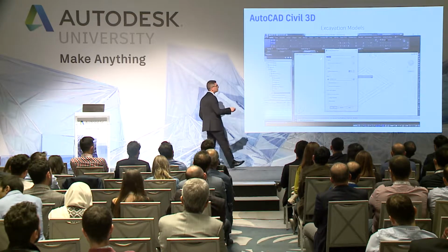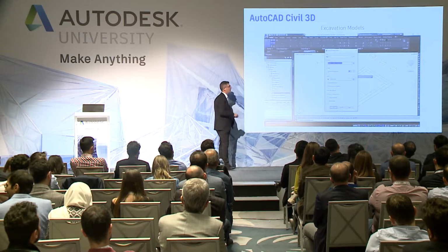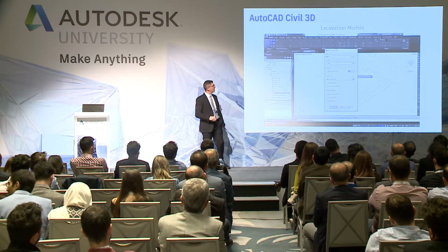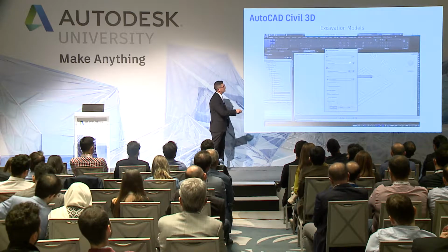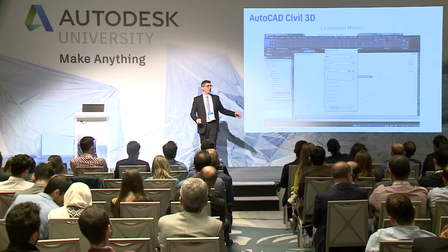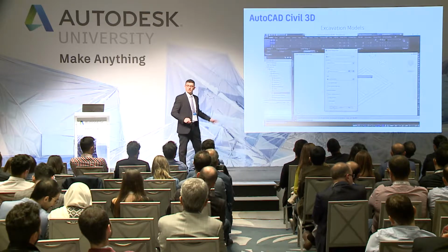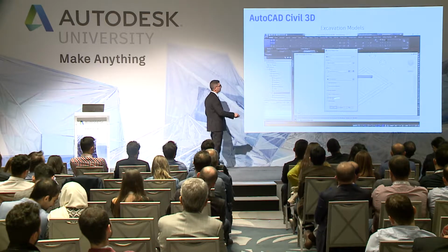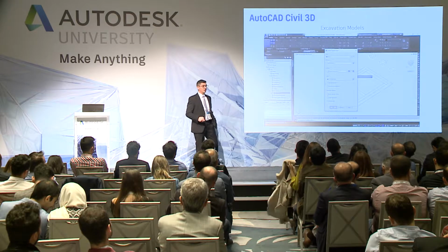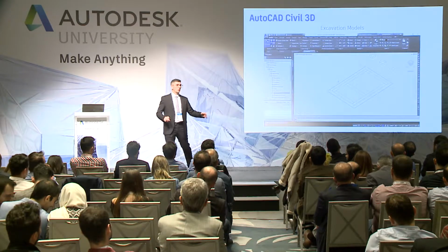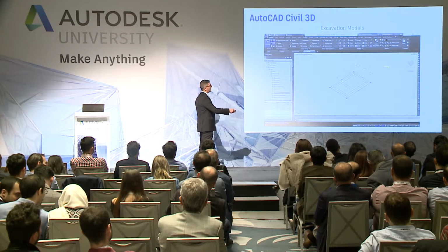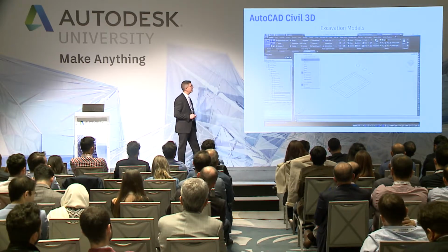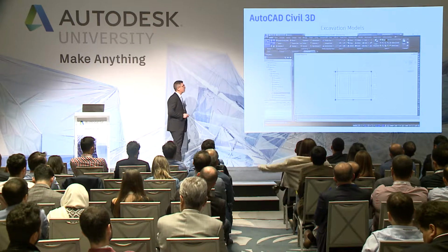This is a site. It's a special part of the Civil 3D tool space. But the basic is the name, and again, the style. The style is the color that I want to see inside this building. And again, the elevation. I can assign the elevation at the start, or I can change the elevation afterwards, OK? Then, OK, this is my feature line, and then I can switch again with all the elements.